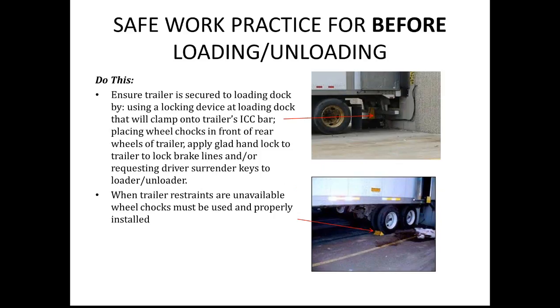Next thing to do is, so many facilities these days are equipped with what we call a trailer restraint. There are many different types, but essentially they all work off one basic premise, which is the restraint comes up, in French it's called a crochet, or it's a hook that locks to the ICC bar. So that's one of the ways of isolating the equipment.